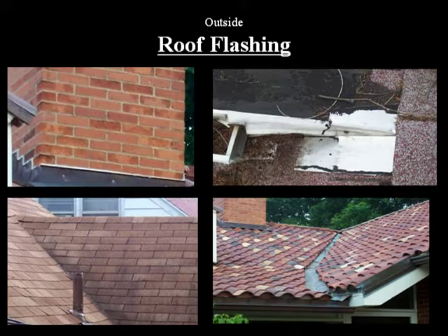Many problems can arise from a stone chimney because of the irregular shape of the stones. Also, if your chimney rests on a downslope, be wary of the back side of the chimney. Water will often pool there. When we do our attic inspection, we'll look for signs of leakage on the upper side of the chimney.